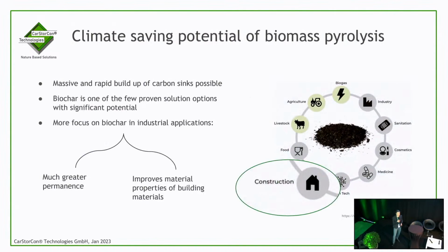Also for the biochar side, it can maybe mitigate a bit one of the problems that biochar always faces, where it's seen as not being so permanent, because we see what happens actually if you put the biochar into a cementitious matrix. It actually really is integrated in the mineral structure, therefore very, very high durability, even over several recycling cycles, can be ensured.